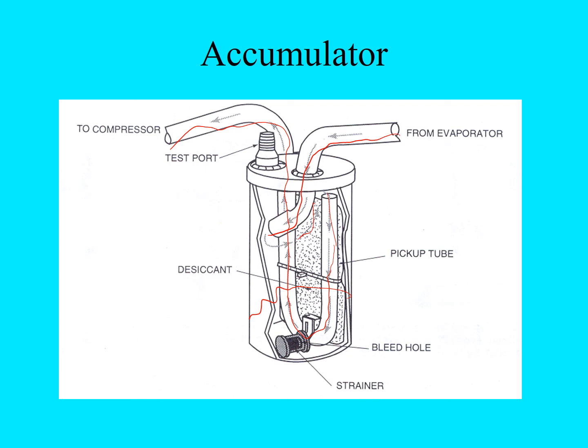Inside the accumulator would be a desiccant bag, okay, and that's this component here as shown. And that desiccant bag is to absorb any moisture that may have got into the refrigeration system. We don't want air and moisture in the refrigeration system. So in the service procedures, which we'll be getting into in part 2, we would actually pull all the air out of the refrigeration system, put it under a vacuum before we introduce the refrigerant into the system. So this is the accumulator.